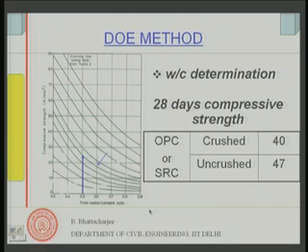One way is to take the tabular values, but that will give you only one curve. That is not really the right thing, because this has come from some results which have been done in the UK and will not fit the Indian situation. To fit the Indian situation, I must have some data, suggested that I should have one 28 day strength at 0.5 with my aggregate and cement system.